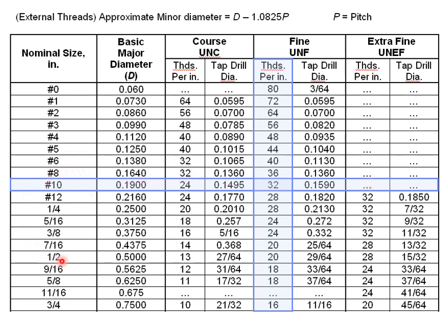Okay, let's take a look at ½ inch. A very common bolt that you'll see in a machine shop is 1/2-13 coarse thread. If you want a finer thread, like inside of an engine bolt, or maybe wheel studs, then you'll go with fine thread, ½ inch-20. A common stud in a Chevy will have a 7/16 wheel thread, 7/16-20 fine thread. Again, you're dealing with high RPMs, so you go with fine thread, 20 threads per inch, versus the coarse thread, which is 14 per inch.